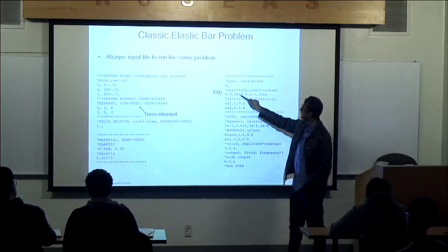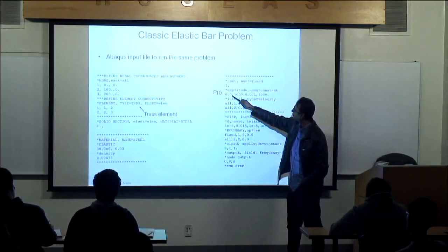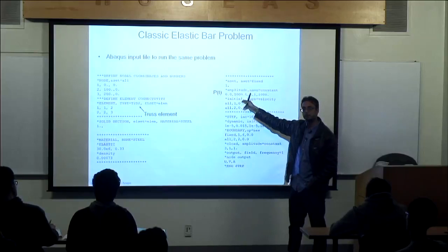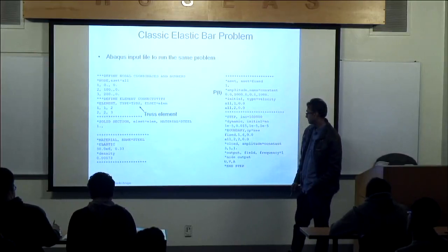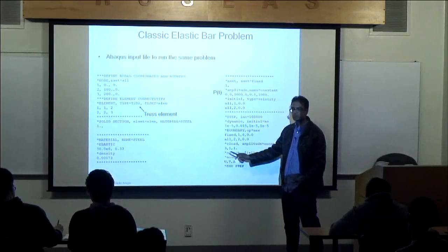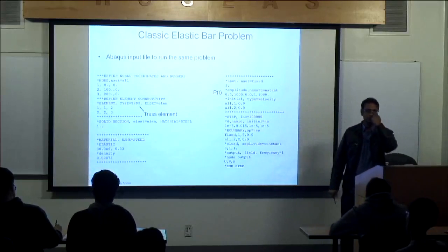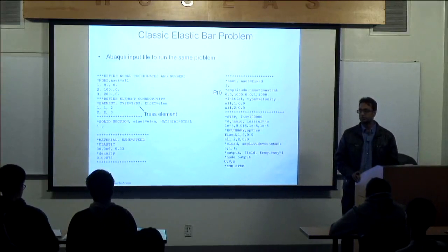You define that. If I give you a sine curve, like a sine input, you will input that here. You will input that sine curve in there, and you will reference it here with 1.0. And then I just get the node output. I ask for velocities and accelerations and displacements. I ask for all of them. Any questions on these particular points that we made so far? That's just how to set it up by hand in Abaqus.